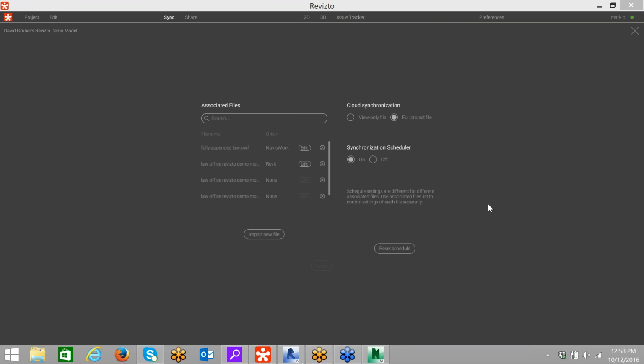The group comes in as one issue, and underneath the chat box, as you guys saw me typing in, that will show you a breakdown of all the clashes that were in that group. So if there were 15 or 20 clashes, it will show you the details of each of those individual clashes. You can bring them through as individual clashes or group clashes. We know that's important, if you have one team that's creating 23 clashes, we want to make sure that only comes in as one issue. So yes, that comes through as one issue per group.